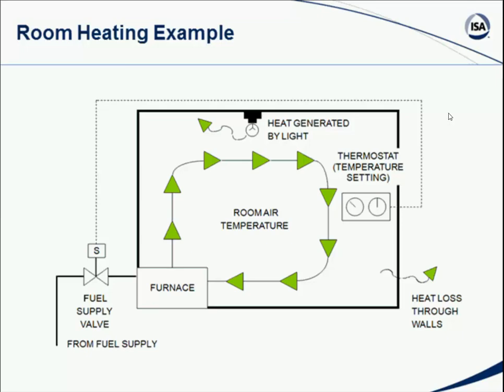In the room somewhere, we will mount a device called a thermostat. The thermostat is actually a multi-purpose device. First of all, most thermostats have some kind of a dial or user interface that allows you to set a desired temperature, as we talked about in the last lecture, something called a set point. This is where you say, I want the room to be, for example, 70 degrees Fahrenheit. So you dial in 70.